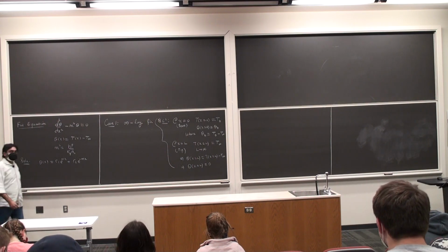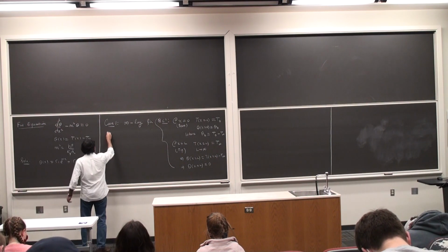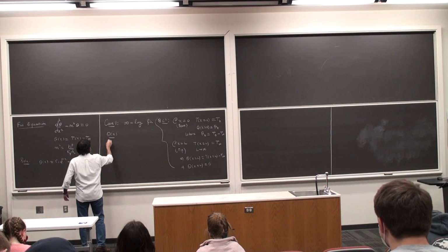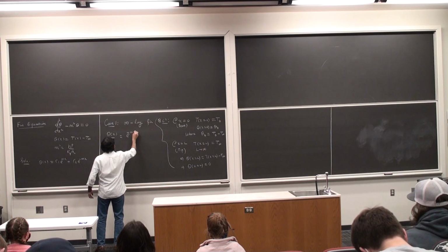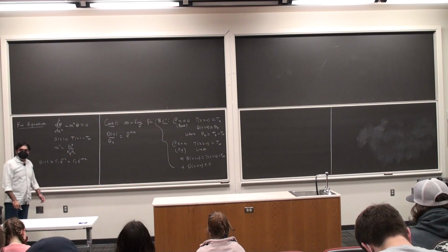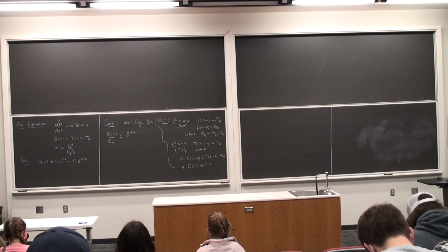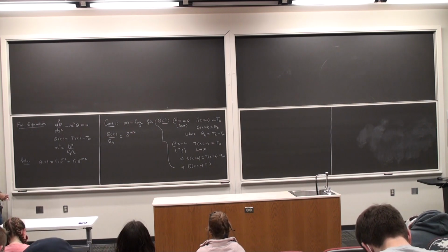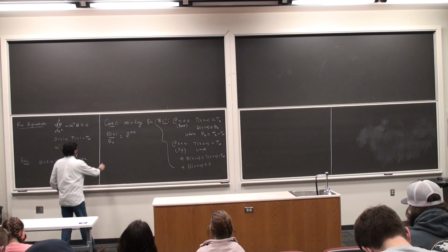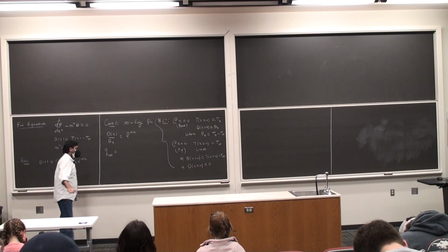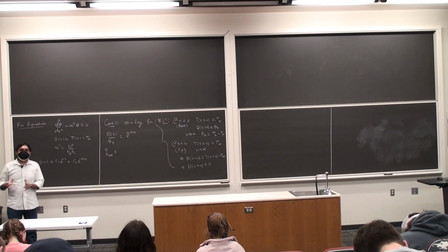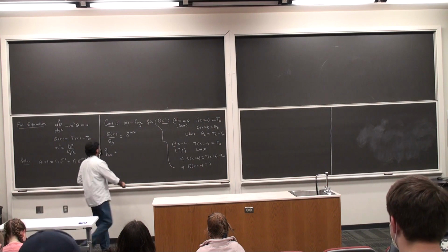So two boundary conditions, two constants, C1 and C2. I can solve for the constants, and so I end up getting theta of x over theta_b equal to e to the power minus mx, no surprise, this is an exponential solution, okay. And then I can also solve for the heat loss rate, Q loss, and I had a small schematic to go with this last time. I'm just going to recap that, okay.